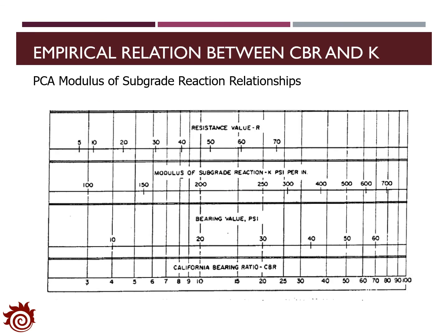In addition, we can also explore the relationship between CBR and the modulus of subgrade reaction from the empirical data. The figure below shows the values of different CBRs with respect to different moduli of subgrade reaction. You can see that roughly if the CBR is around 80, the modulus of reaction for the soil is 700.